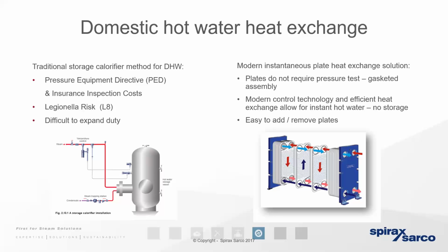But even though it's got a relatively large footprint, it's got a very low surface area, a low A value. Whereas if we compare that with a plate heat exchanger, if we've got a number of plates all stood up on their end, it takes up a very small footprint of space. But if we laid the plates out side by side on an area across the floor, you could appreciate it'd have a very large A value, or a large heat transfer surface area.